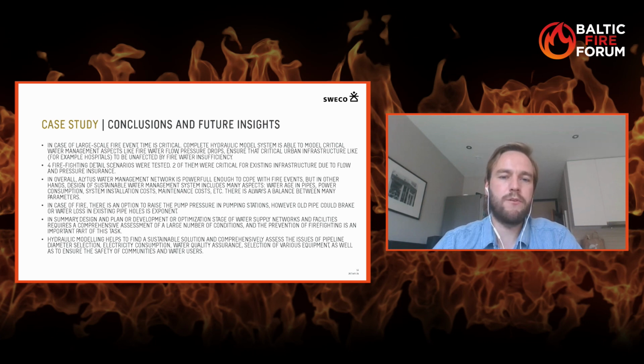Complete hydraulic model systems are able to model critical water management aspects like fire water flow and pressure drops, and ensure that critical urban infrastructure like, for example, hospitals will be unaffected by fire water insufficiency. 4 firefighting scenarios were tested. 2 of them were critical for existing infrastructure due to flow and pressure insufficiency.